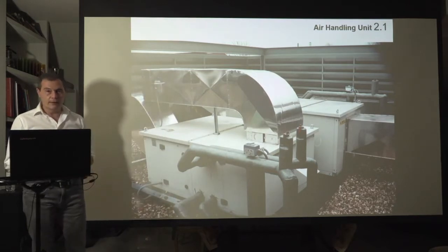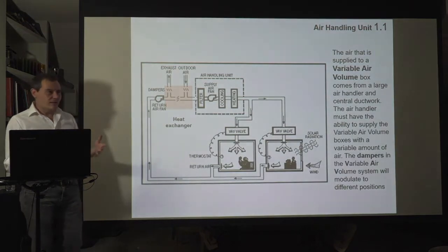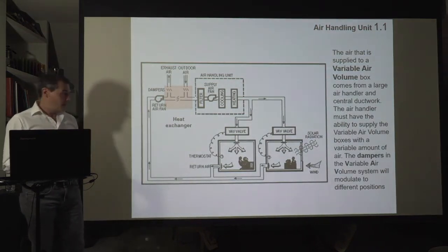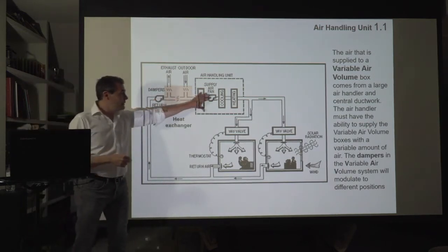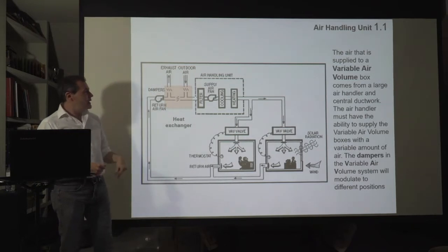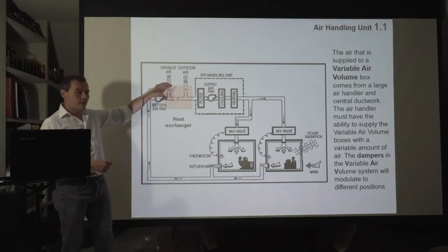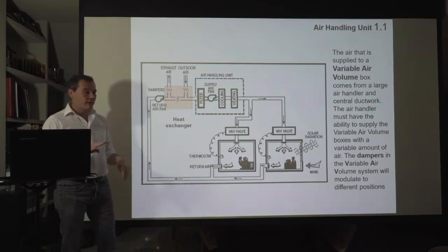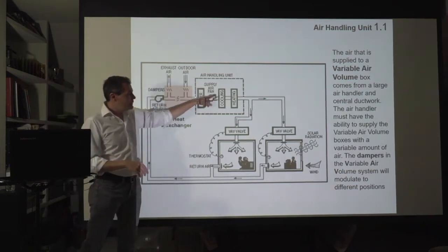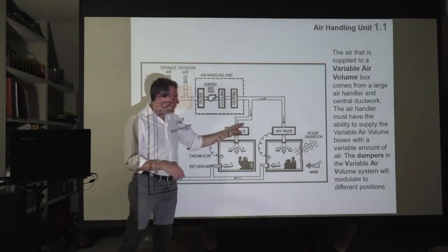This is an air handling unit. And this is the schematics. Then you have to become familiar with schematics of buildings. Here we have the air handling unit, we have the exhaust air, the intake, the return. So here that would be an air handling unit with 4 air ducts. And here we have filters, cooling coils, heating coils, we have the fan, and then we have the ductwork.